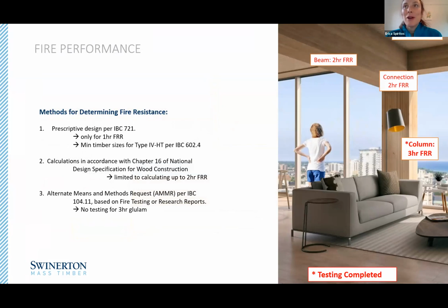So the fire rating requirements for the building were as I described, and we used this CHAR calculation methodology to validate the fire rating for the beams. To validate the fire rating for the columns and the CLT panel, we actually tested those products. So that was number 3, what you see here. We actually performed testing, and I think, Sam, that might be your next slide.